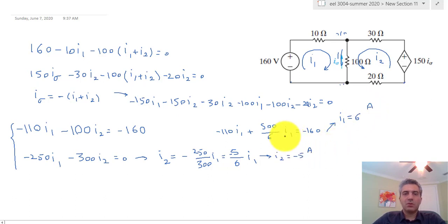So now with these two, you can calculate all the voltages across the components. Keep in mind that these are the voltages across the components. For example, if you take I1 and calculate the voltage across the 10 ohm, that would be 10 times 6, which is 60. That's not this voltage nor that voltage, it is the voltage difference. And if you recall, this potential, assuming that you take this one as ground, turned out to be 100, and this being 160 gives you a 60 volt difference using the other two methods.